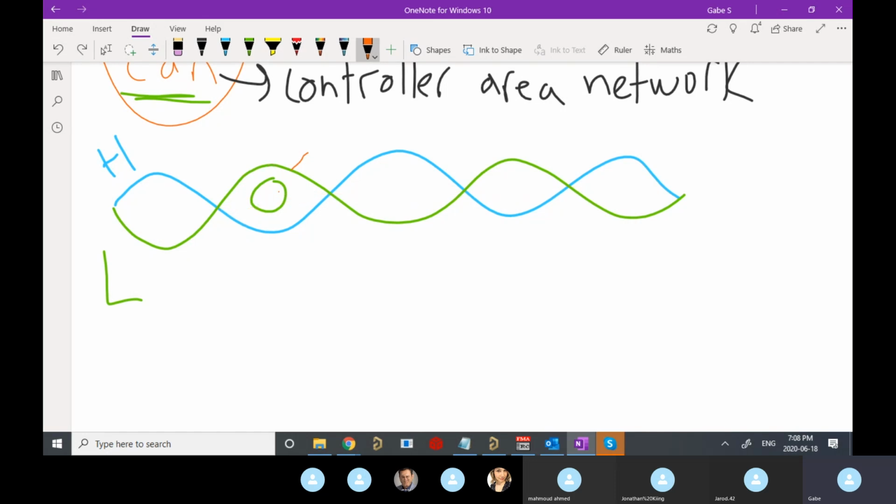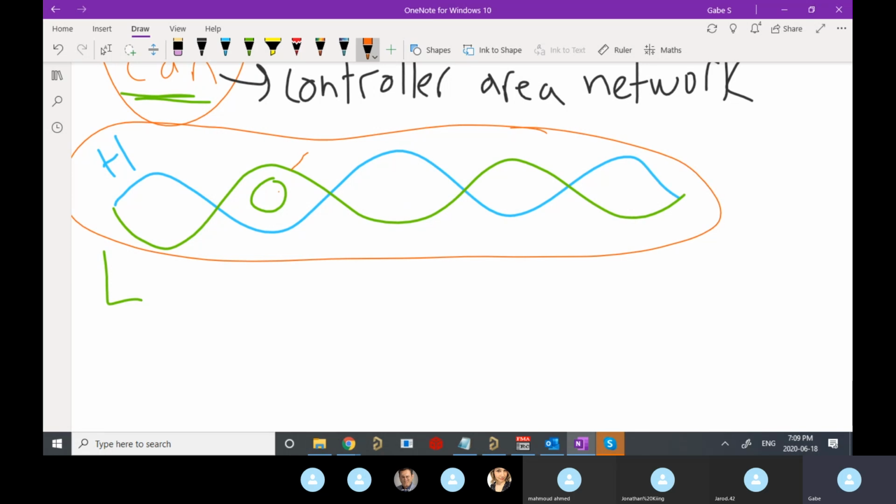So that's great. The reason CAN is more robust than something like UART is because the 2 signal lines are a differential pair. What that means is that they basically act as one line. Even though they're 2, you don't get that transmit and receive operation that you do with UART, right? It's not full duplex. You can only send and receive one thing at a time.